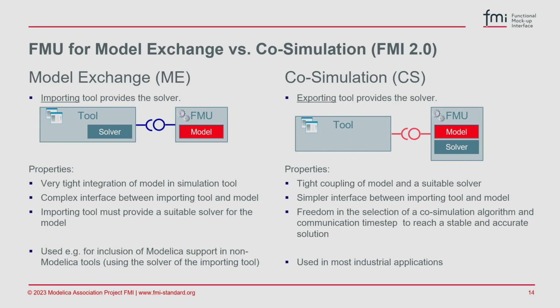And for model exchange, which I will explain now, there you have the notion that you have the model inside the FMU, and the solver for this differential equation, this is outside. This is coming from the importing tool.